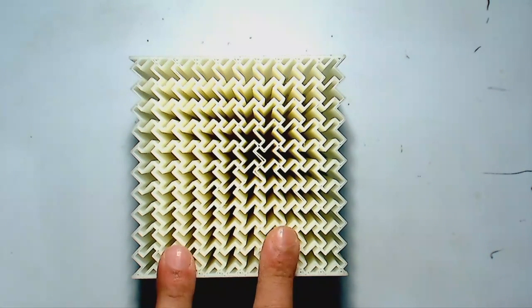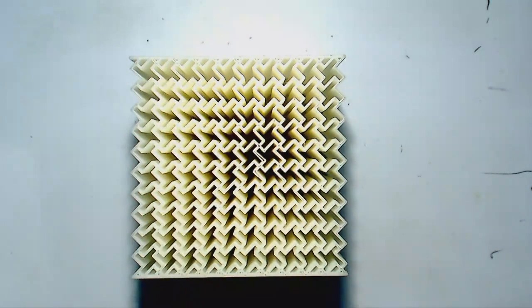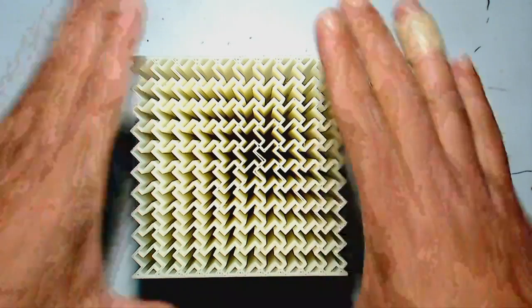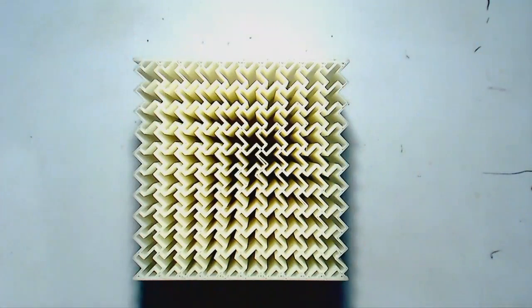So these auxetic structures are quite an active research area, to come up with different forms of structures that give a Poisson's ratio that is positive. Poisson's ratio is negative from the material point of view, but you can arrange the material in a certain structure. I had a paper model which I could have demonstrated that effect to you. I'll bring it to the next lecture.